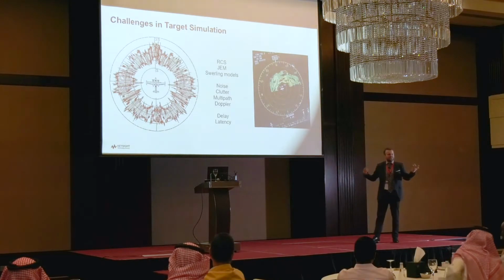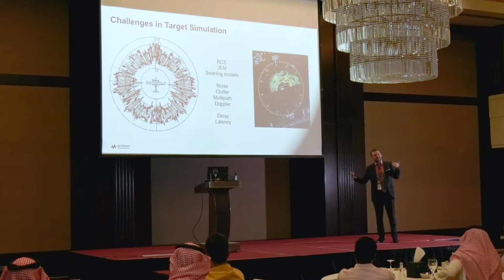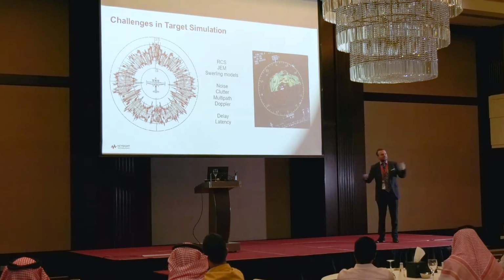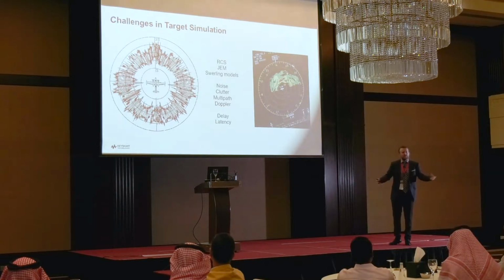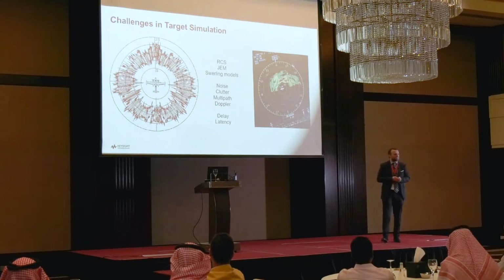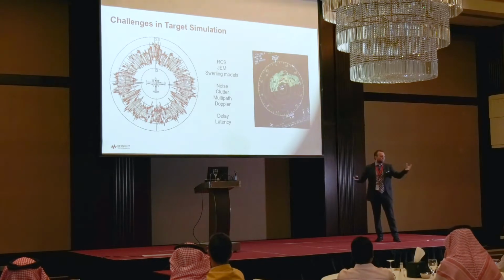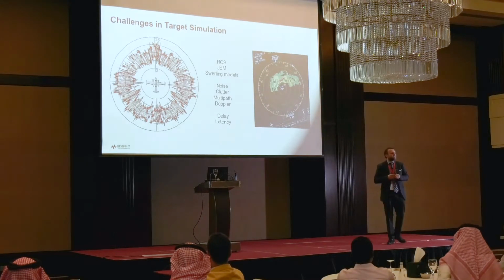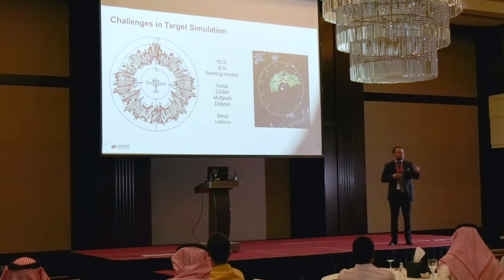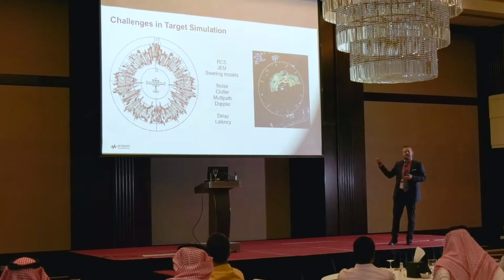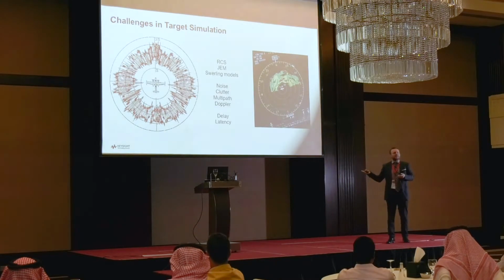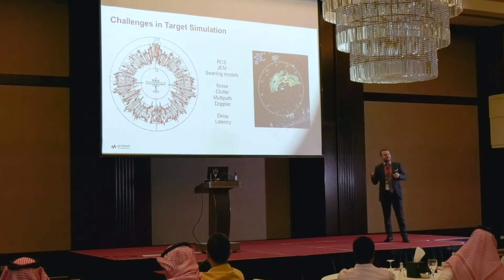So 10 nanoseconds is 3 meters, which means if we're looking to change something about an aircraft that may be 10, 20 meters long, we have maybe tens of nanoseconds to react to the radar pulse that's received.